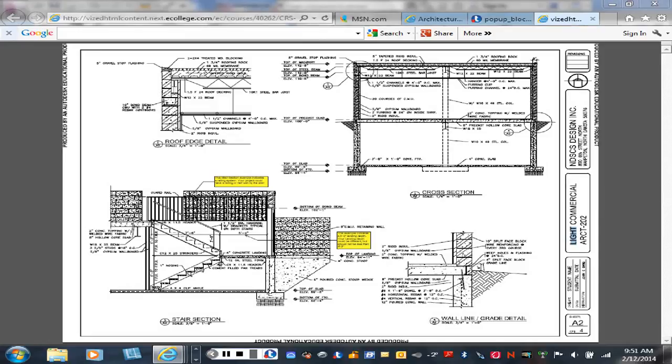And that's what we're seeing right here. So we're coming up with 8-inch block, and then we're probably going to 6-inch or 4-inch blocks, whatever it works out to on getting up to the top. In this case, our parapet probably won't be very high above the roof, maybe a couple inches. If we wanted it higher, we'd obviously have to go another 8 inches maybe or whatever to get it above.